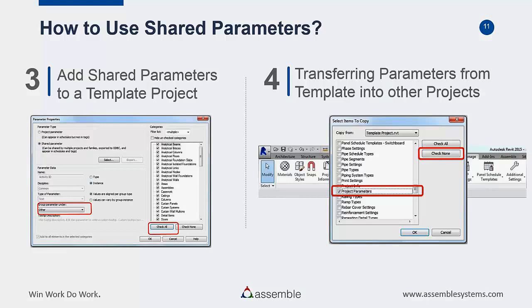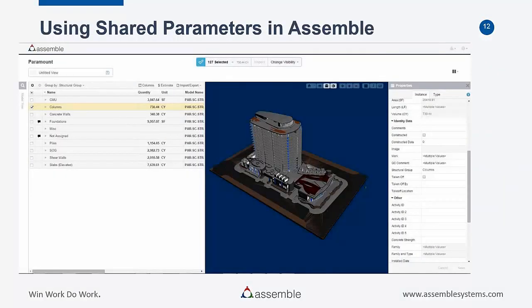So that's really nice to know that even if you're not the author of the Revit model, this is a way that you can utilize those parameters. Now, if you don't have Revit at all, you're going to have somebody create these parameters for you. If you want to use mine, they're also linked in the handout to a place where you can download all the project parameters that I've created for this workflow.